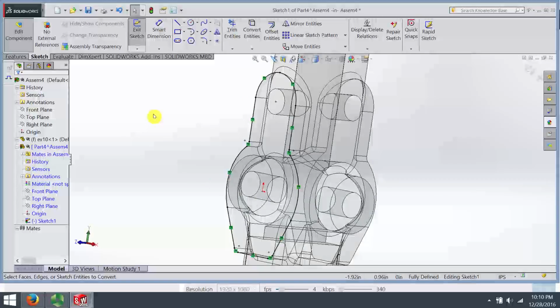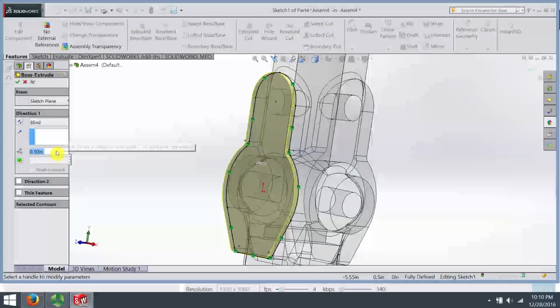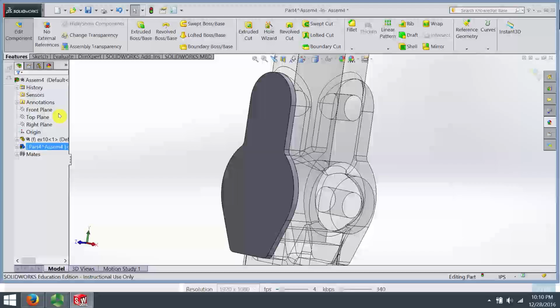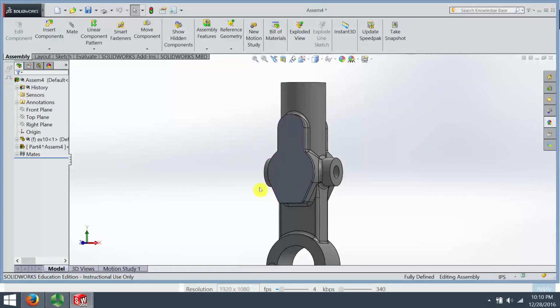And so now I can turn it into a part. It's just a sketch until I turn it into something. So now I'll go to Features, go to Extrude. Let's make that a full 1/8 of an inch thick. 0.125, say OK. And it's not exciting, but there's my first part. Now just close this right here. What that's saying is stop editing that particular part. You can either click this icon here, or click this guy here, and it'll get back to the full assembly. Right now we're just kind of looking at a ghost of the rest of the assembly. So I'll pick on this guy, and now we can see I've got two parts. I've got my original, and I've got this little cover.